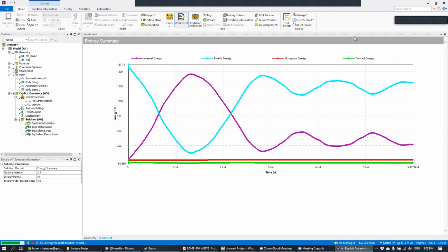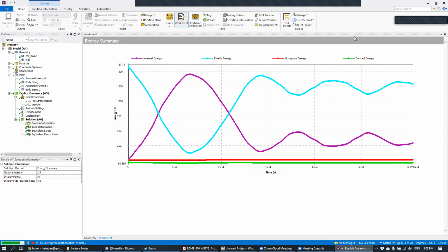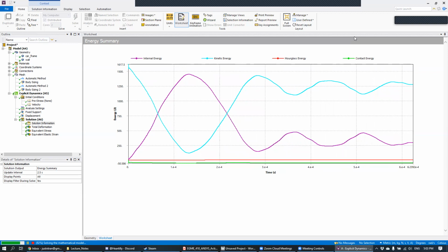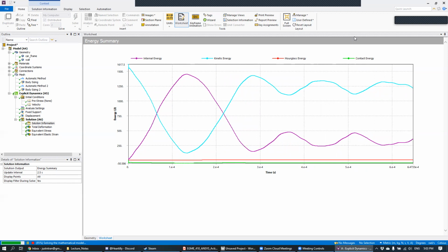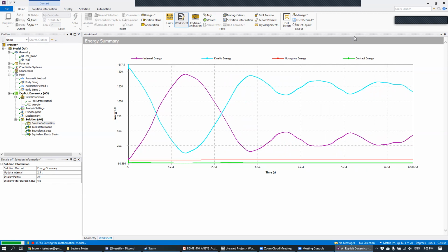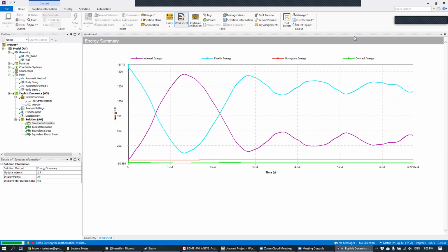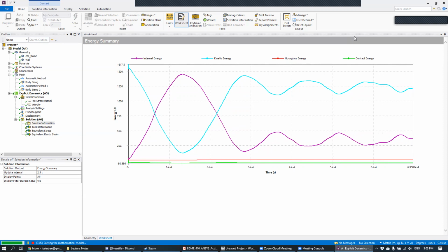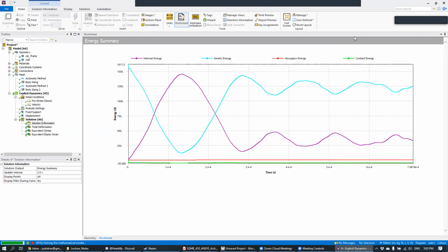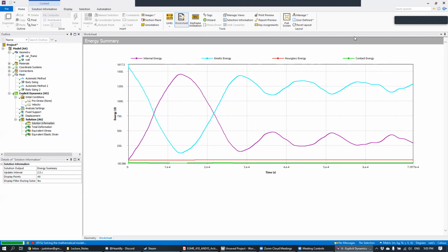But besides that, based on what we've learned in this class, the best approach would just be to iterate. You would run a simulation under a certain configuration, and then from there you would say, okay, maybe I want to thin out the geometry here, or maybe I want to try a different material here, and then make those adjustments, run the simulation again, and go based on that. There are some automated tools like the topology optimization, which we'll learn. But a lot of it's going to be largely iterative, on different stuff that you're going to try manually.